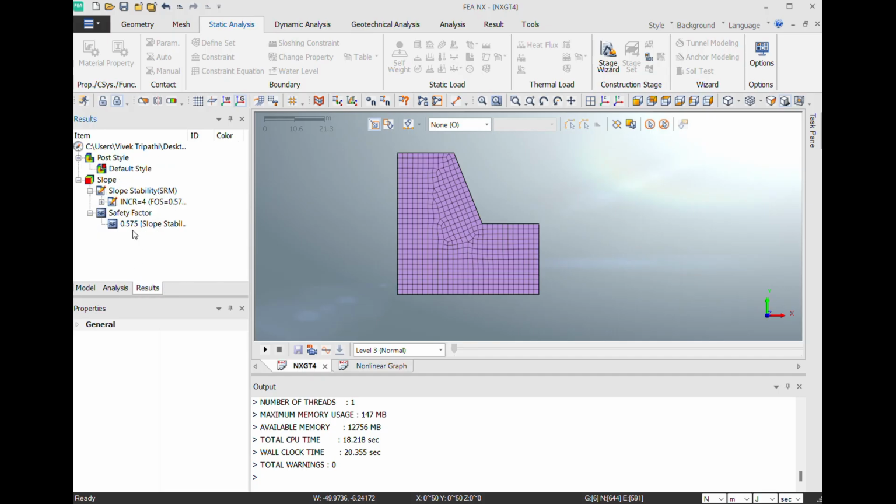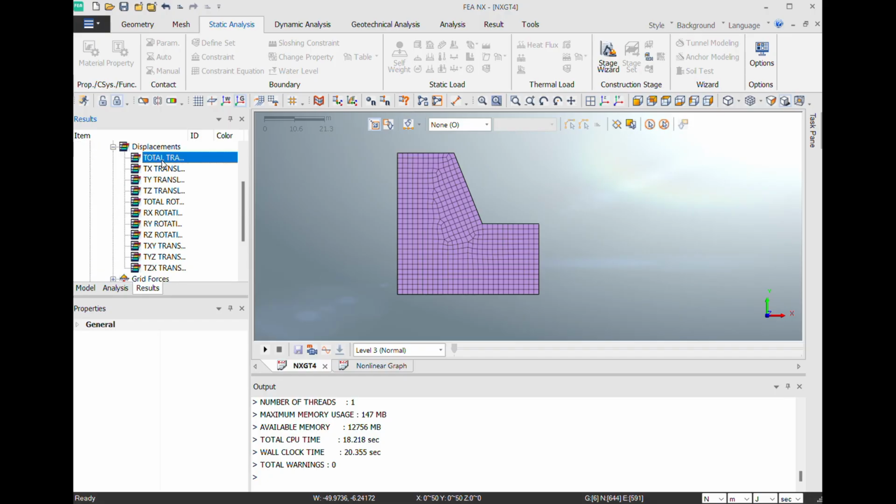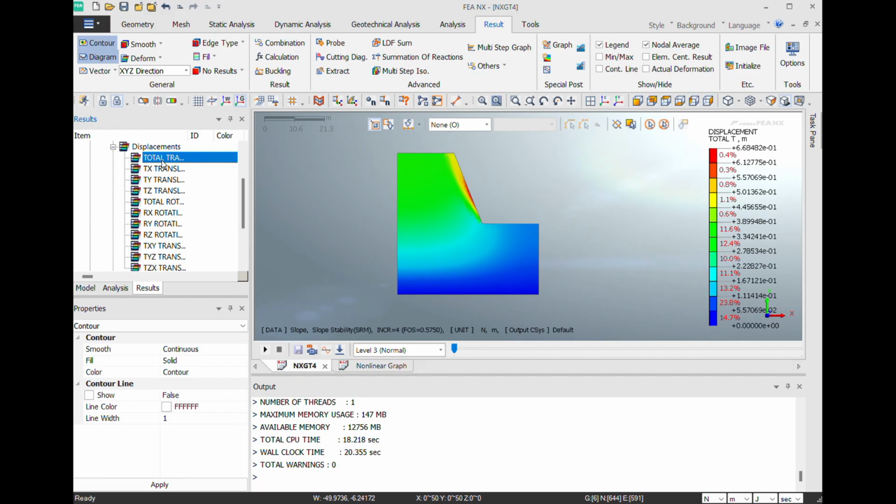Once the solving is completed, we can see the results. As informed already, results are checked in a different tab next to the Analysis tab. In the Results page, we have different options to check our results as per our need. We can check stresses in different directions, settlement or translation in different directions. Also, we can get the information of particular values at different nodes.